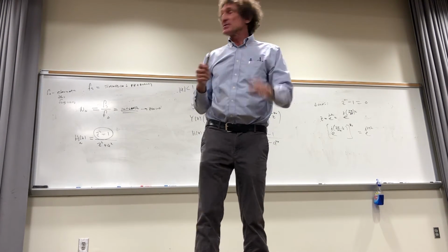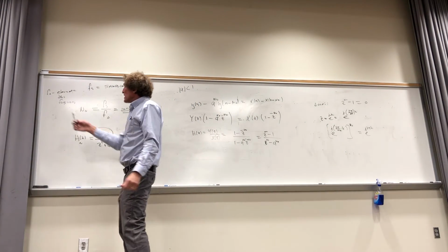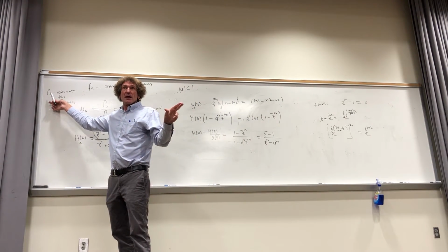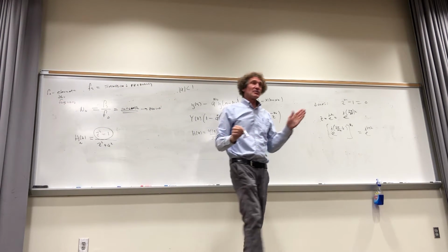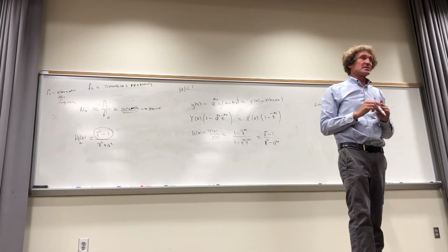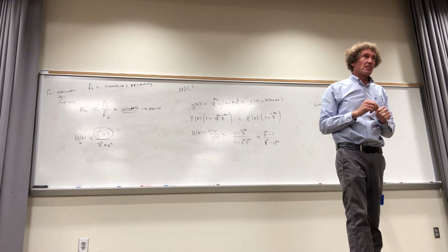Because the harmonics are going to be at what? Not at F naught, at what? 2 F naught, 3 F naught, and they're always integers there, and they always land on top of this notch. It repeats itself and it gets rid of them. Do you follow me on this, class?